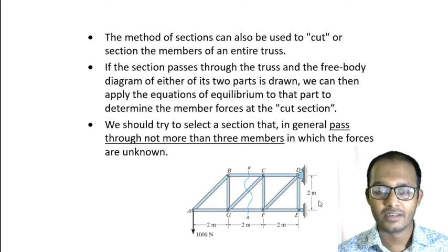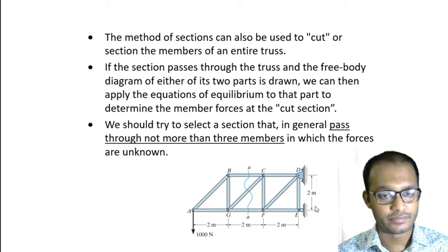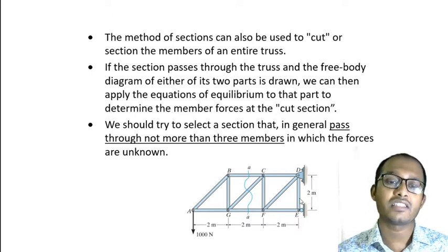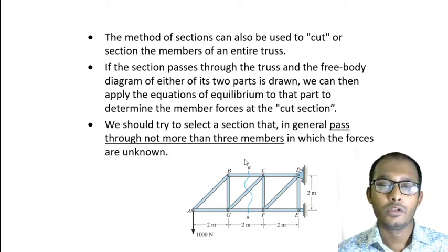Do you understand? So I cannot cut from here. If I need to determine the force acting in FD, I will not cut from here; maybe I will cut from somewhere else. It will not be a wise idea to cut exactly from here. We need to cut at such a position where there are not more than three members.